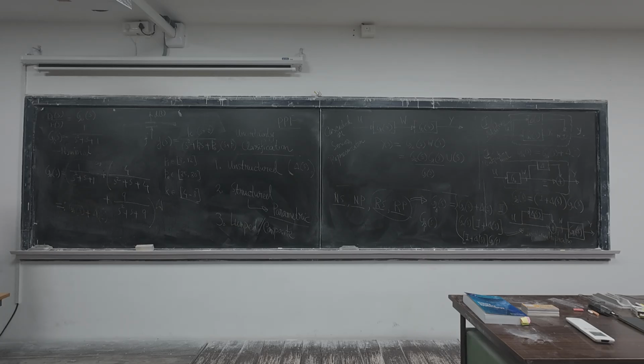Then how many modes will be of our interest? That really matters. So how many modes will you be considering? Those whose strength, that is magnitude, can cause some trouble in our controller design. That many modes you will have to consider. It can be 15 modes, 20 modes, 25 modes, something like that. But ultimately, this model never becomes equal to the original system. That is one of the reasons why it is called unstructured.